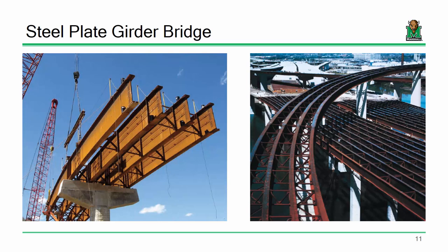If you've got something like this horizontally curved flyover, just how you detail it such that you can actually put it together so that these cross frames will fit together during construction and that you don't generate massive additional stresses, that can be kind of challenging and a little tricky throughout the construction process and throughout the design. So stuff like that's things you've got to consider.